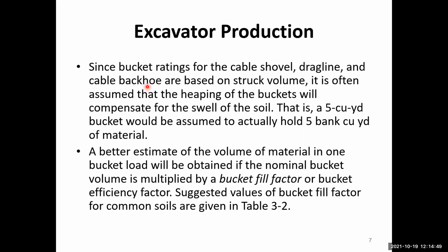But due to the swelling, we may assume that, for example, a 5 cubic yard bucket would actually hold 5 cubic yards of material. Although that 5 cubic yards of material in the bucket will be in the loose condition and in the heaped condition, and the overall loose volume will be more than that, we may assume that. So it may be a simple assumption for this purpose.